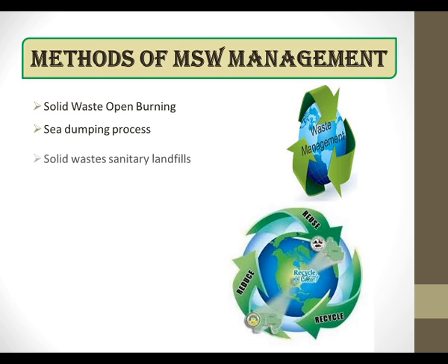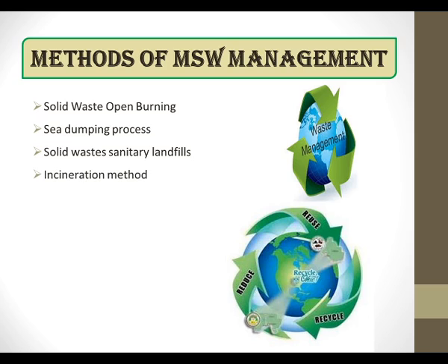The next process is solid waste sanitary landfills. The sanitary landfill process is simple, clean and effective. In this procedure, layers are compressed with mechanical equipment, covered with earth, leveled and compacted. The next method is the incineration method. Incineration is suitable for combustible refuse. High operation and construction costs are involved in this procedure. This method would be suited to crowded cities where sites for landfilling are not available.